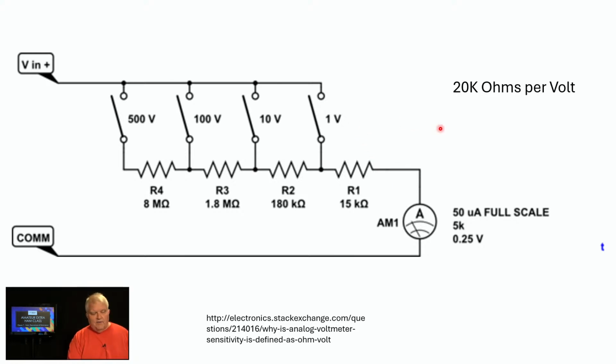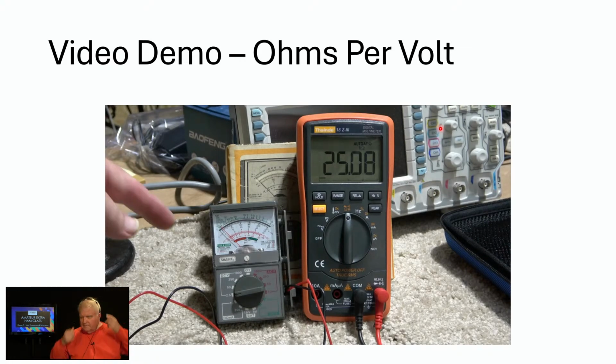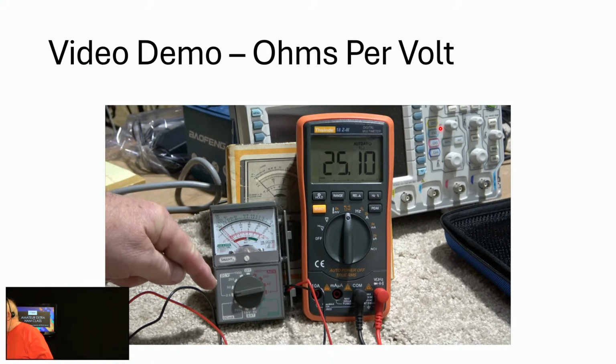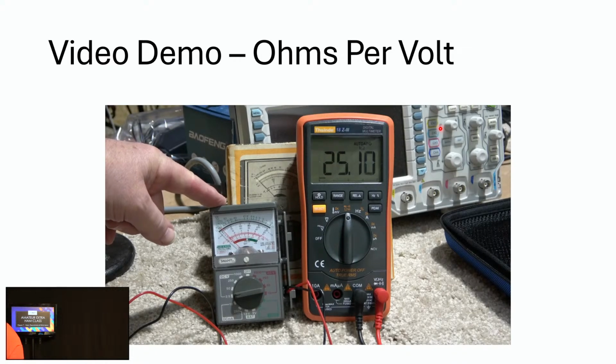And let's go back down to the workshop, and I'm going to measure one of my smaller meters. I want to demonstrate the concept of ohms per volt using this small snap-it analog meter. It's set on the DC volts 2.5 volt scale. This little meter is rated at 10,000 ohms per volt.